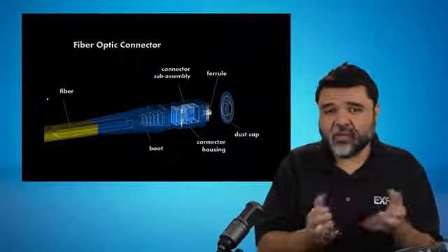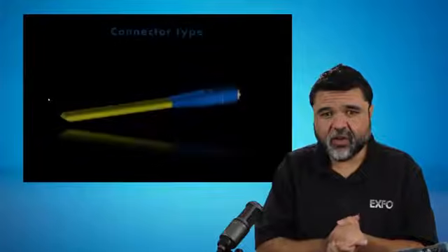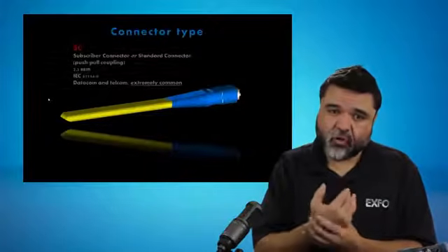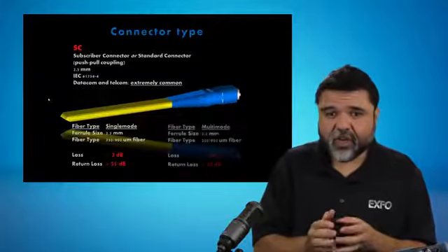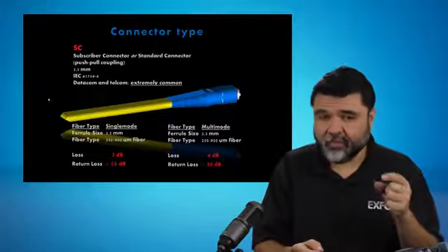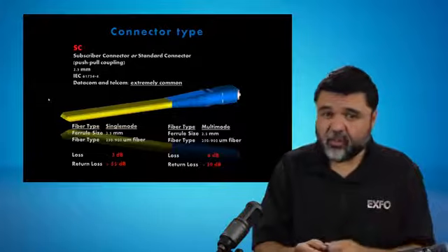So your connector housing here in the United States, a lot of companies have standardized on the SC connector, the subscriber connector. So here they call it Sam Charlie connectors. And so with the Sam Charlie connector, it is a 2.5 millimeter ferrule with the square housing on it.